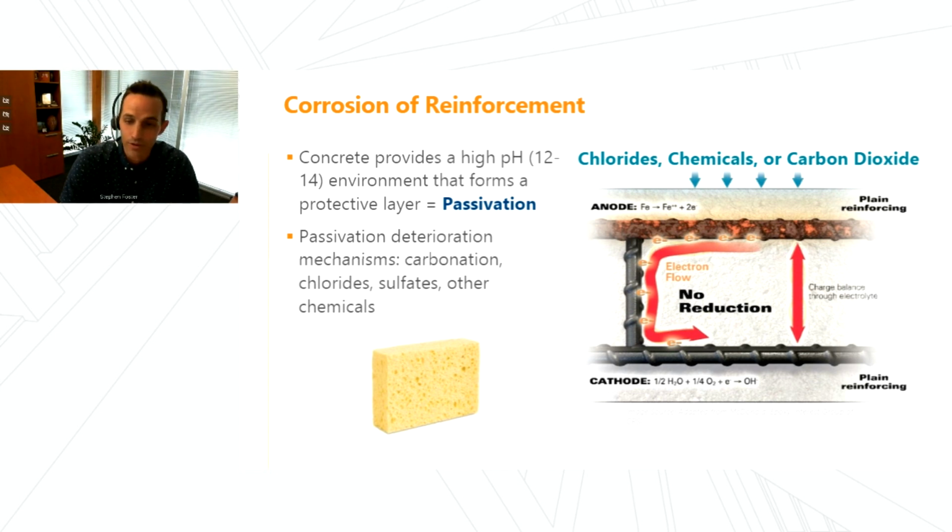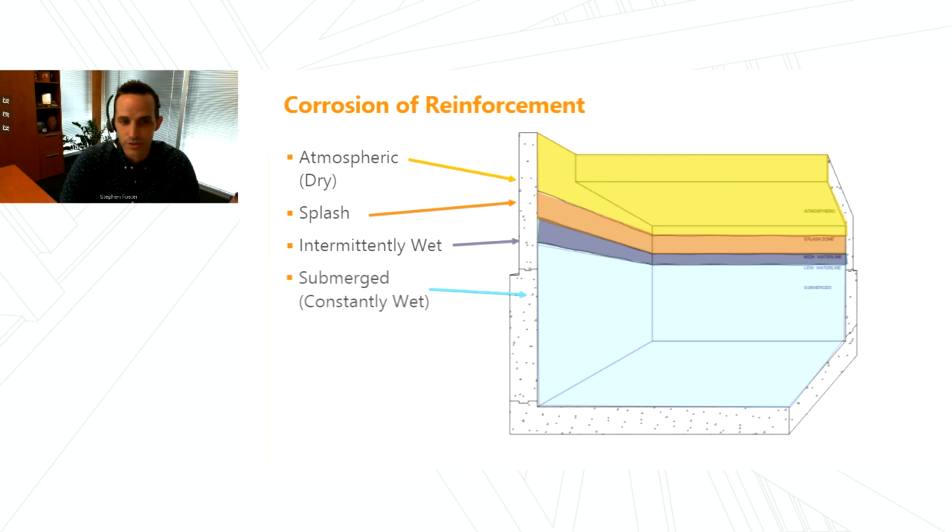And not only that, but with regard to water and wastewater environments, there's usually some variability in the exposure zones too, right? Like we're showing here on a tank structure, there's an area that's going to be constantly wet and continuously submerged. That corrosion process is going to need oxygen to promote that chemical reaction and the chemistry that occurs there with the corrosion cell. So maybe that might be a little bit better in terms of long-term corrosion performance, but then there's these other areas that can change too.